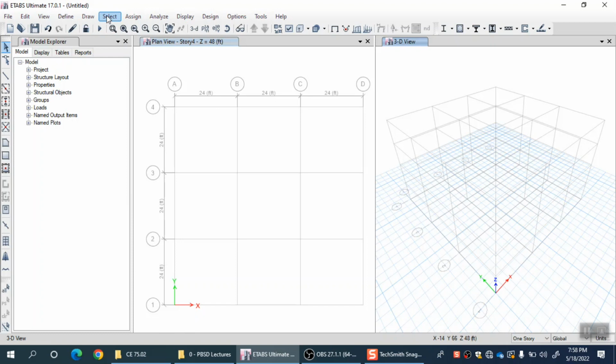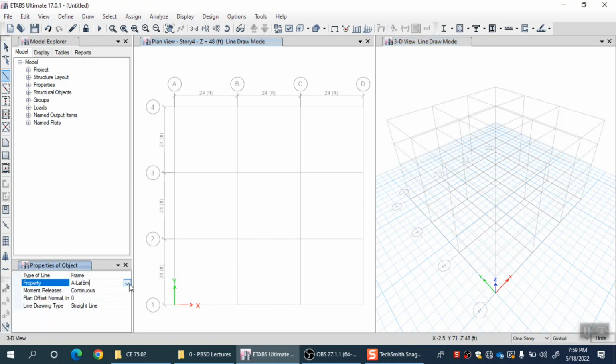Instead of doing that, we directly select a beam and directly assign it the auto hinge using ASCE 41 table. So the program will do that whole process for us if we provide the basic inputs required to enter in that table. The program will directly pick the values from that table and define that hinge, or populate that whole hinge form for us, right? So let me first quickly draw a particular RC beam, an example beam.